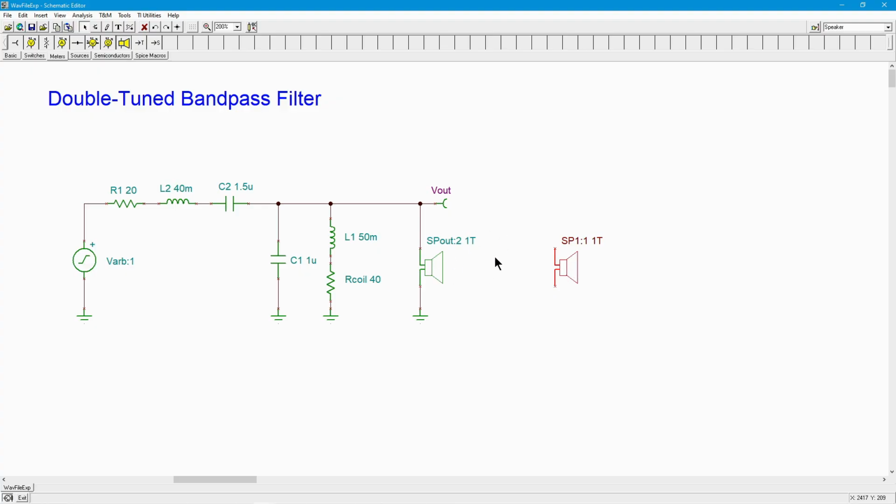Now you might be asking a question. Why is this like :1 after the name and this is :2? This is one of those little cool things that Tina has that may not be immediately apparent to most people using this. I mean, I used Tina for a few years before I discovered, quote unquote, discovered this. The number after the colon allows you to specify where in the output window you want the waveform to occur. In other words, if you don't have the curves all collected together, if you have them separated, this will tell you the order in which they're going to be.